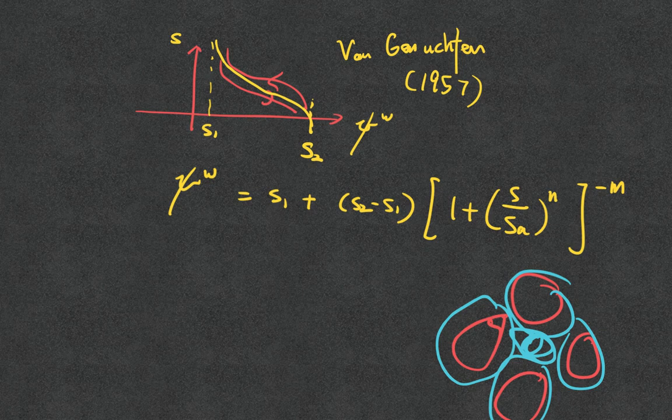Of course, if the whole thing becomes completely saturated with ice, then it doesn't make sense, because the ice will be so big that it cannot transport anyway, right? And then there will be no water thin film when it is completely frozen. But before it is completely frozen, the water is supposed to be surrounding the soil. So the water thin film surrounds the solid and the ice, so that the ice doesn't form attached to the solid. Okay, these are the assumptions.